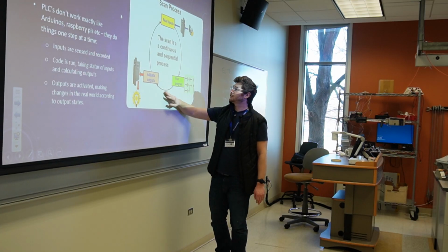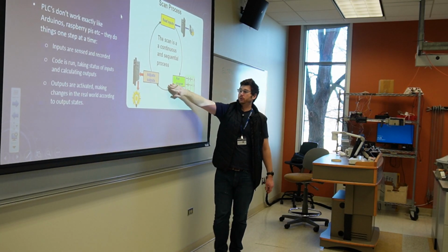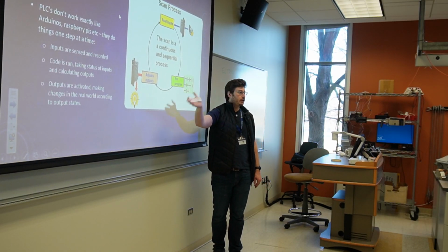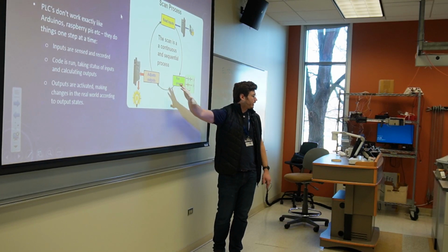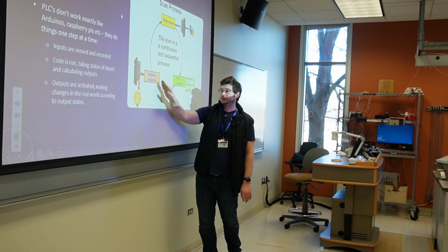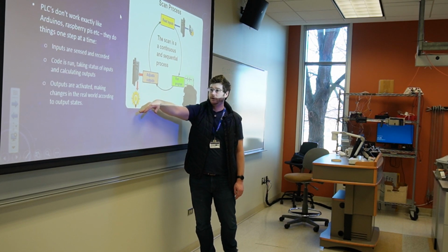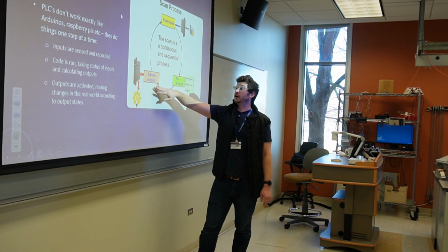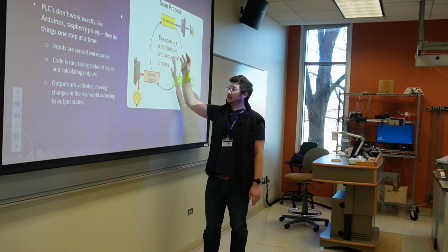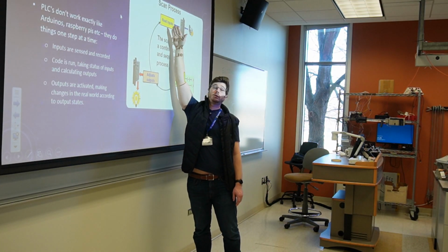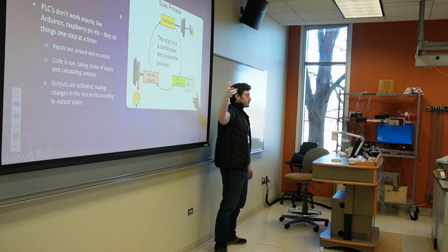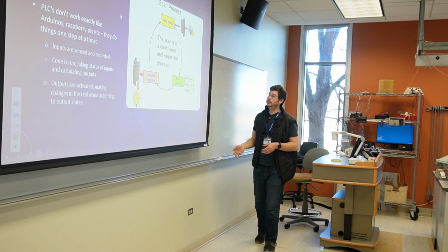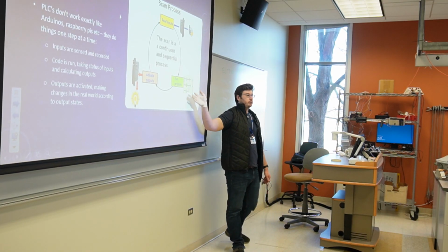There's actually another more advanced step in between run program and adjust output, which is a communication stage. That's when we have like PLC to PLC communication, logging for talking to the internet. That'll happen right here, things like that. But otherwise, it'll just go right to the outputs, right? Turning things on and off. Writing to our transistors, so to speak. And then we start it all over again. So this is, our program is said to have run. It is now 10 milliseconds later, and we're gonna go and run that program again. We're gonna refresh our inputs. What are they now? In this new instant in time, 10 milliseconds later, in this new reality. And what should we do with those inputs, and so on and so forth.